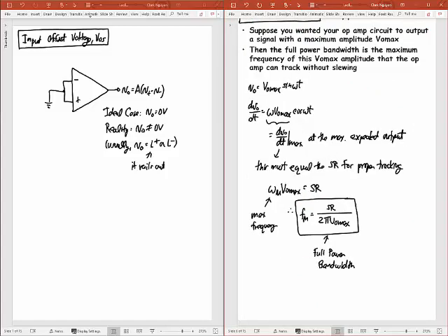And so the way that we model this, and that's all we're really doing, we model this with an equivalent circuit. Okay, and that equivalent circuit contains an input offset voltage source that we're adding specifically to model what's happening here.